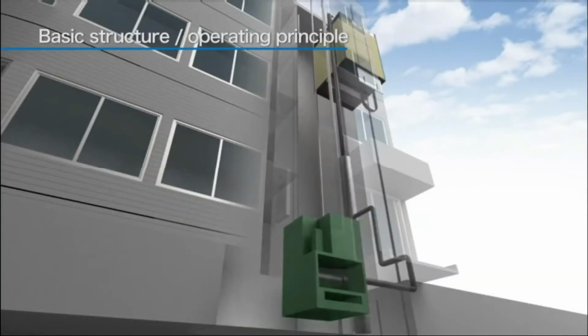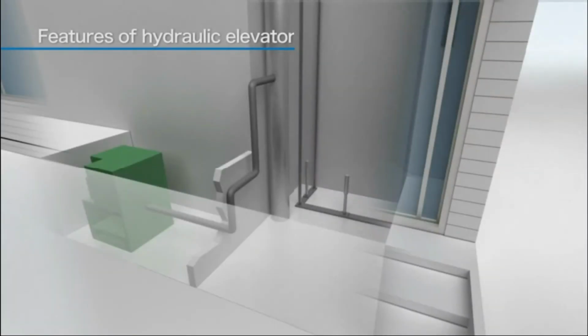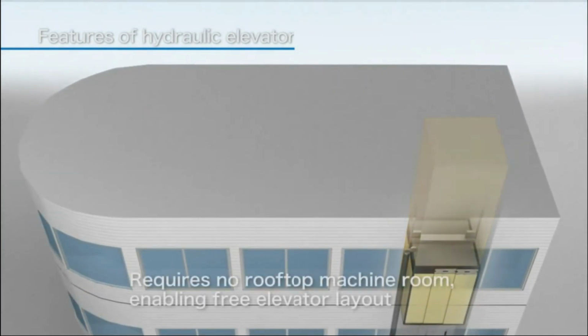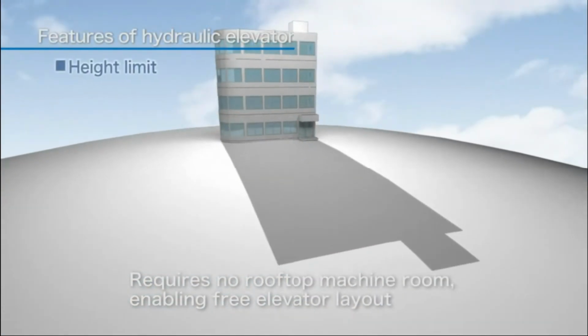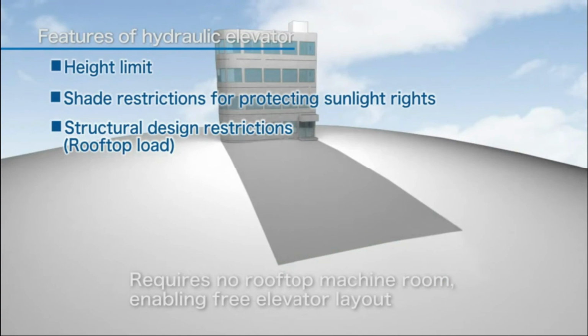The equipment consists of a hydraulic power unit, hydraulic cylinder, and cab. The location where the hydraulic power unit is installed can be laid out somewhat freely, and there is no need for a rooftop machine room. Because of this, until the development of machine roomless elevators, these types of elevators were frequently used in buildings with height limitations, buildings with sunlight blocking restrictions, and buildings with weight restrictions.